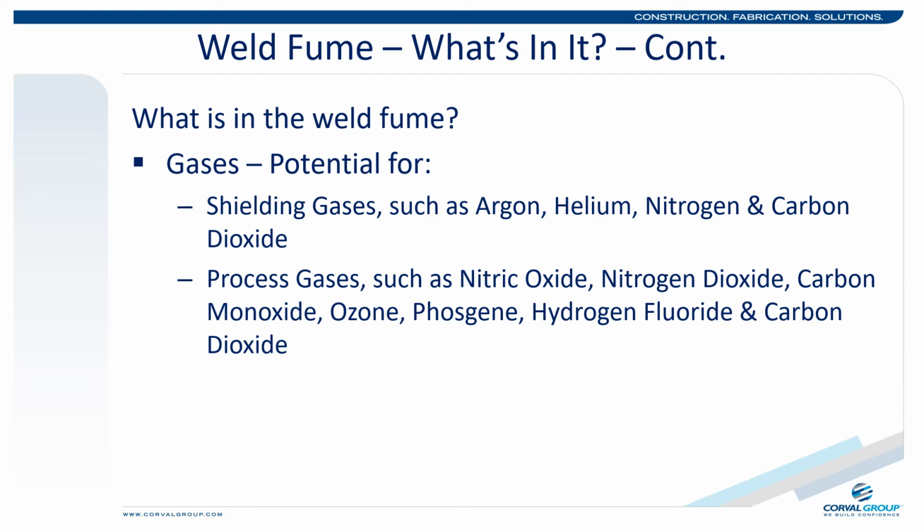Even though many of the gases used are non-toxic, they can displace oxygen in your breathing air. This could cause dizziness, unconsciousness, and possibly death. Process gases are gases that may be produced as a result of the welding activities, including carbon monoxide.